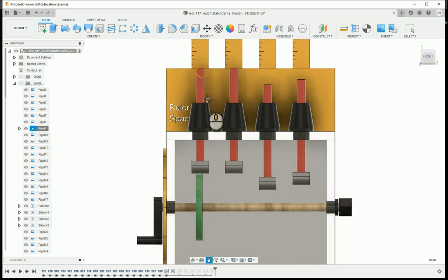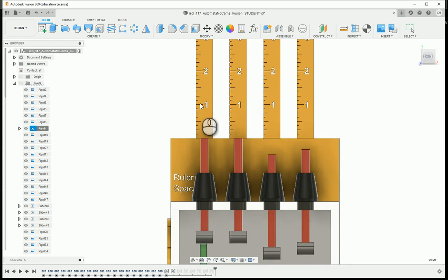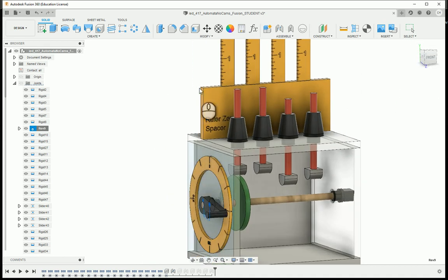You can watch the top of the follower. On these measurements, you're going to the 1/8 of an inch. So there's 1 inch, half of that would be 1/2, half of that's 1/4, and then this one here is 1/8. When it gets down to 180 degrees, it's coming up to that 1/4 inch measurement displacement, and that's exactly what's happening. As you turn this to the side and look at the angle gauge, the follower stays in the 0 position until it hits that 180 degree measurement. So this is one way to get around that issue.